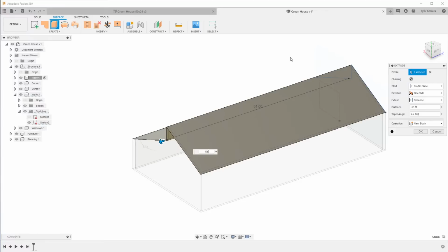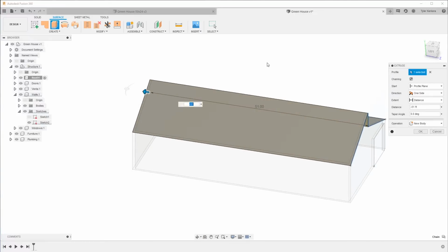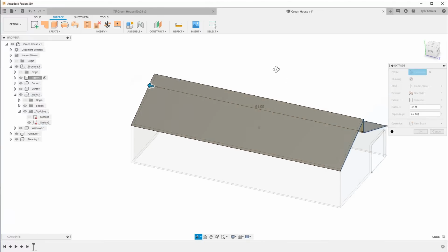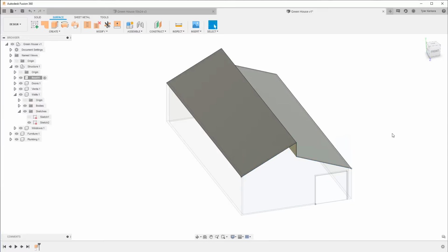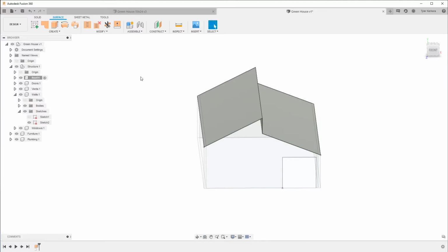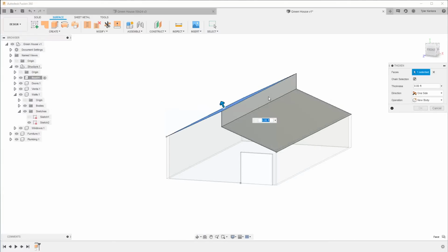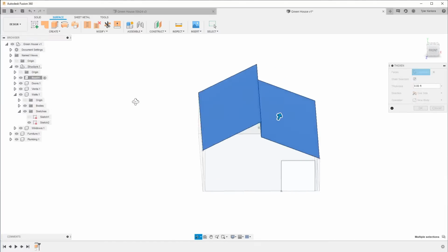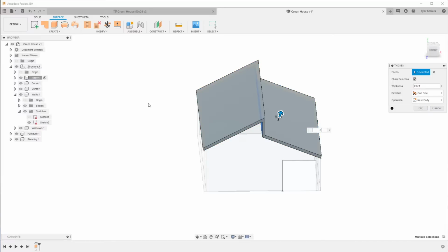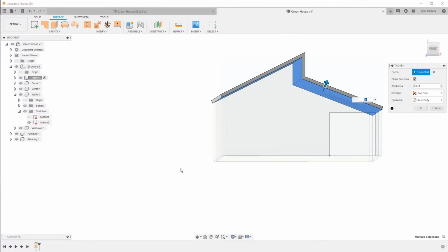That's the interior dimension of that greenhouse plus the thickness of the walls. Say okay. And then maybe I want to add a thickness to this too. Again, the actual way this roof is constructed is less of interest to me than just representing it as some form of a roof. So I'm just going to say this is actually half a foot thick, just like the walls.